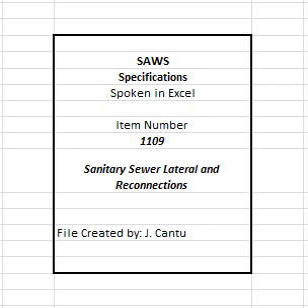1109.3 Submittals. Contractor shall submit manufacturer's product data, instructions, recommendations, shop drawings, and certifications. 1109.4 Construction. 1. Performance requirements. A. Provide a minimum of 72 hours notice to customers whose sanitary sewer service will potentially be interrupted. B. Accurately field locate service connections, whether in service or not, along the new, repaired, or rehabilitated sanitary sewer main.